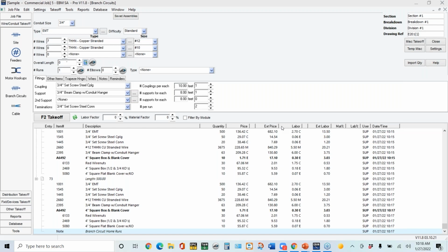With residential, the problem is we can't combine home runs. You're going to have a home run for every circuit, typically with residential, because it's single phase. So it doesn't really help us with the calculation of home runs. You can still use the average length on residential. I think probably the average length for residential is more in the 20 to 25 foot range.